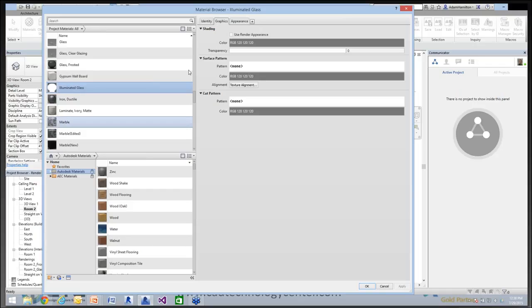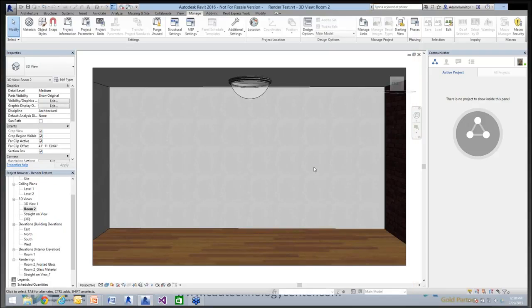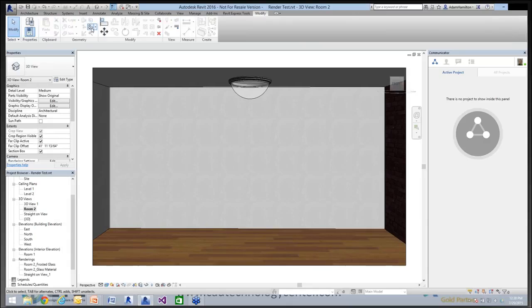So using materials as paint is an excellent way to apply colors to your surfaces without actually affecting the quantification or the materialization of things like floor systems and wall systems inside your project. Again, that was the Modify Paint button. So, adding paints. Like I was saying, there's a lot more to materials, and I really wanted to point out those main portions.